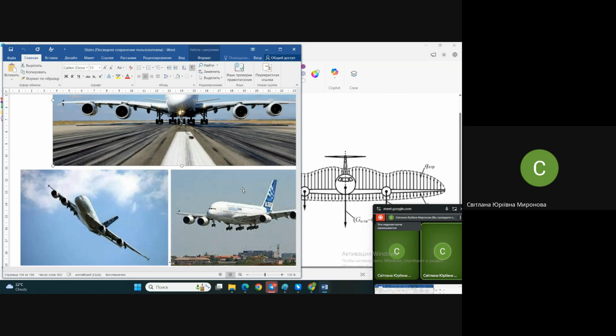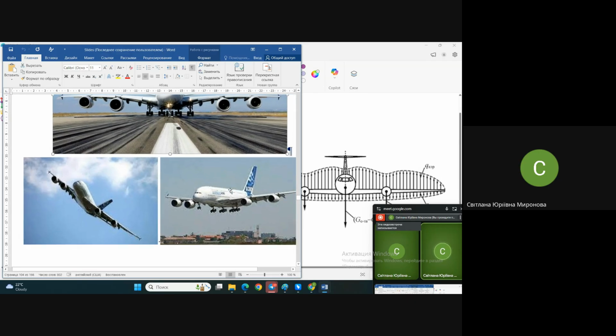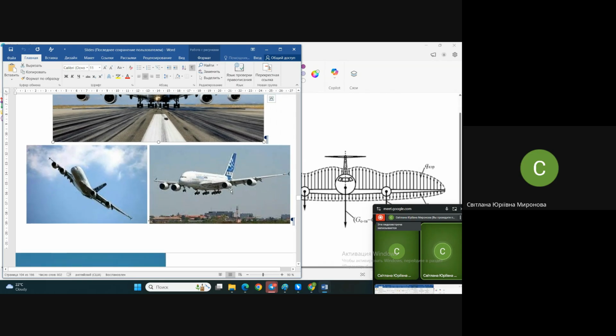On heavy airplanes, it's very, very visible, and you do remember that this one is one of the heaviest. I can't show it on our airplanes because they don't use a low wing. They usually have high wings, and they have another angle of lateral stability. They are not dihedral but anhedral. I mean, the wings are directed to the other side, besides being high wings. And in this case, it's hanging to the bottom anyway.